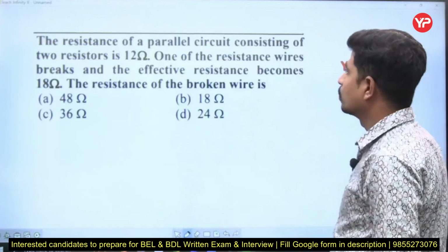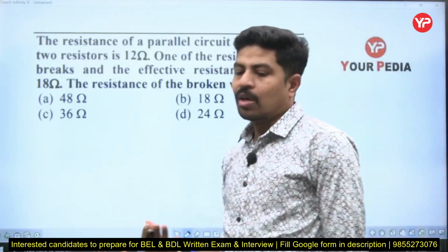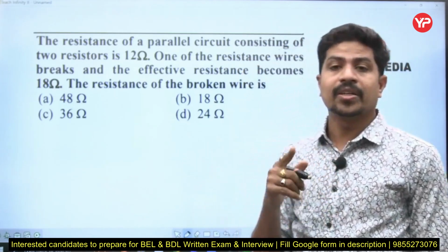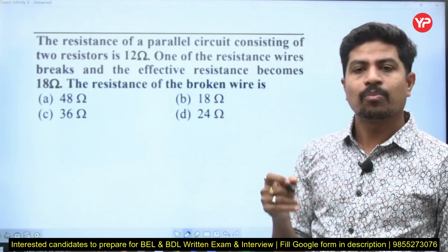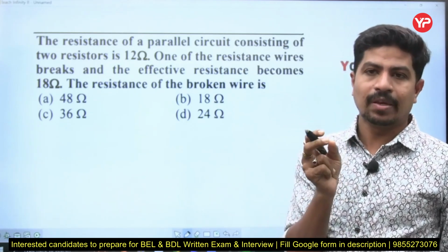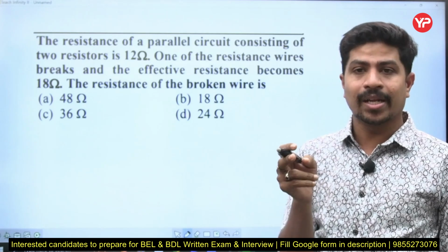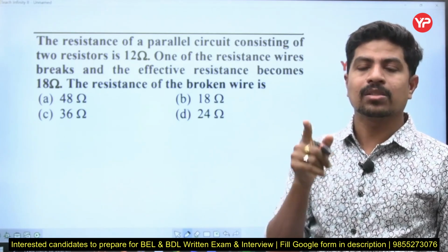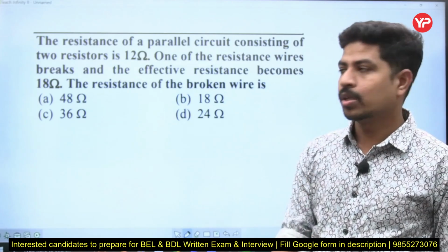Clear? Now, those shortcuts are applicable if the waveform is continuous. If it is discontinuous, the process you have to take up is that you first get the expression for the wave, then you square it, then you mean it, then you root it. RMS: square, mean, root, right?